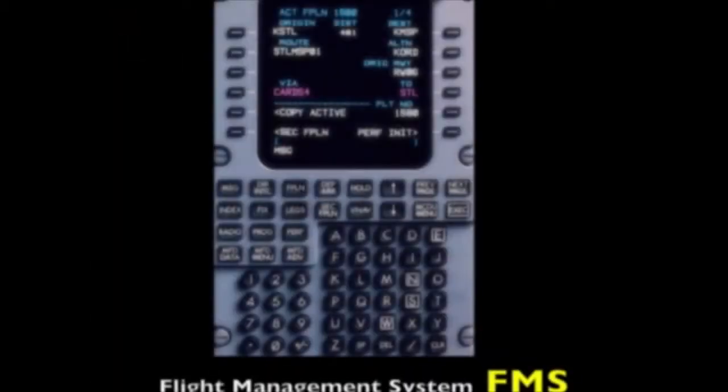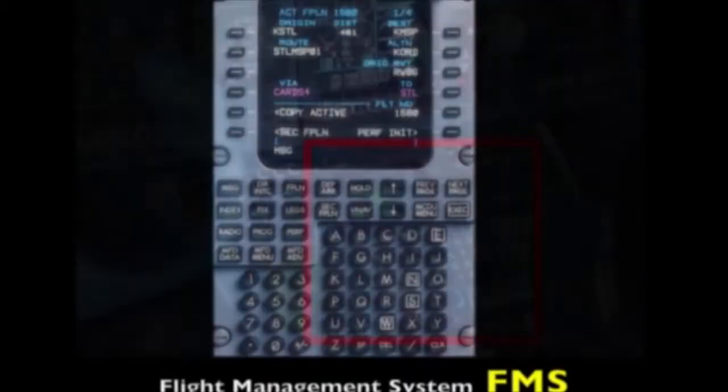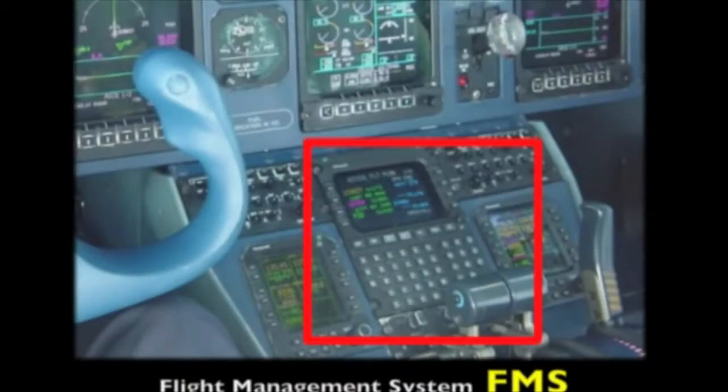The Flight Management System, FMS, uses a large database to help you pre-program your route. The system constantly updates position accuracy. The FMS and its associated database ensure that the most appropriate aids are automatically selected during the information update cycle. This system is normally found in turbine aircraft.